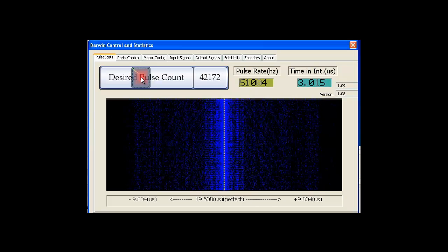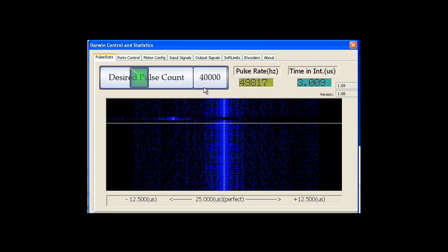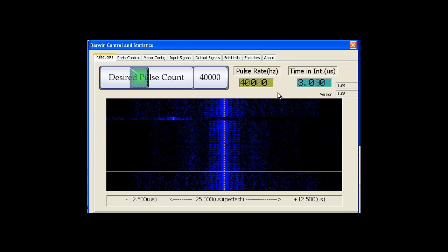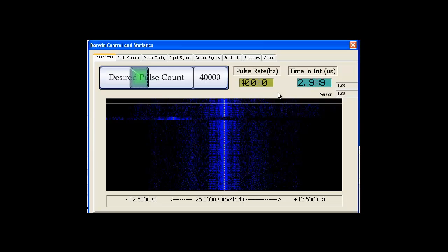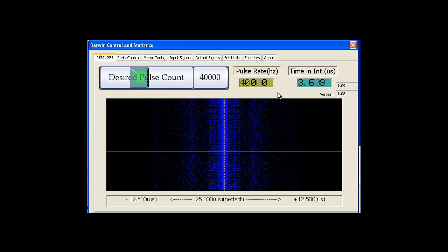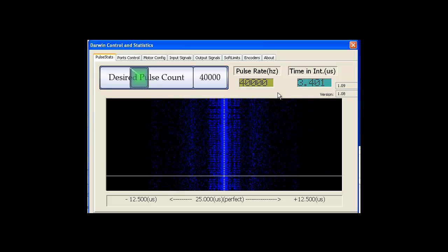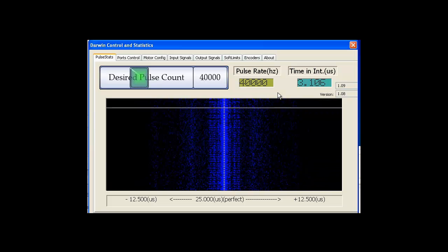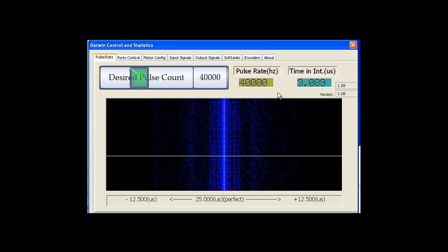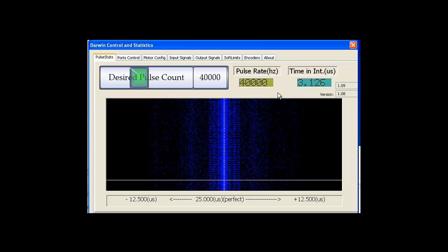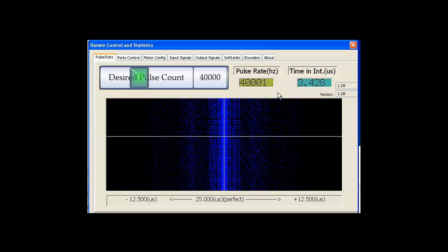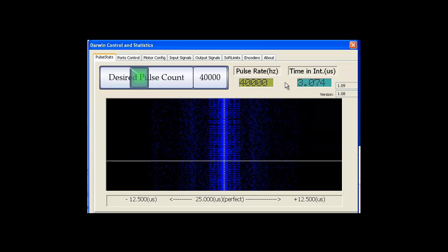As in Mach 3, I recommend using as low a number as you can, which will drive your motors at speed. That allows lots of CPU time for Mach 4 to do its thing. If you find that your system is not being hogged, feel free to slide the pulse count up even higher and reconfigure your system. It will make your pulse train a little smoother the higher it is, but not noticeably so for many, and not at all for most servo users. Servos have their own way of smoothing out pulse train inconsistencies.